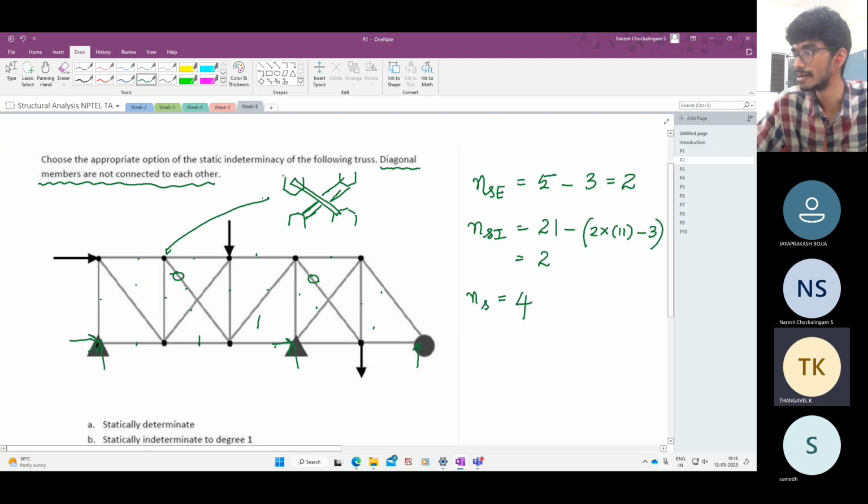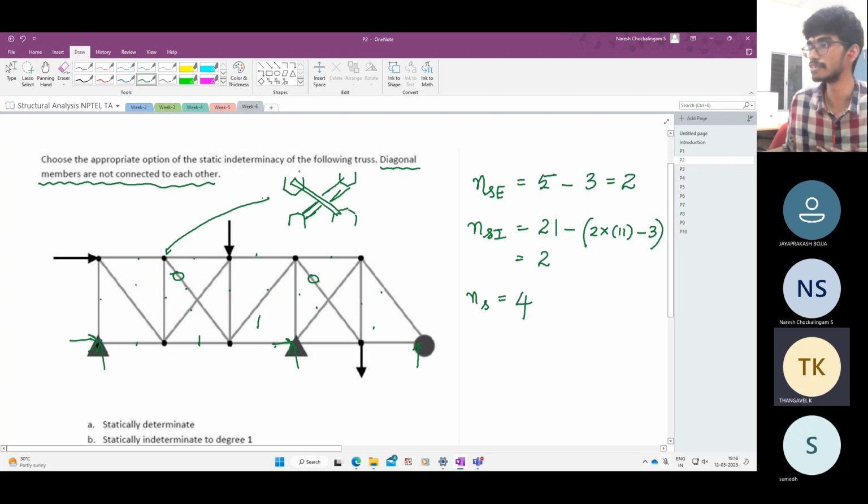Usually it's always in both the directions to avoid torsion. Right? Always they put double angles. But in this case, you can think of a situation like this, where the diagonal members are not connected to each other. Otherwise, if the diagonal members are connected and there's a gusset plate in between which is connecting all 4 members, then it is statically determinate. Internally, it is not indeterminate. But this problem is different.